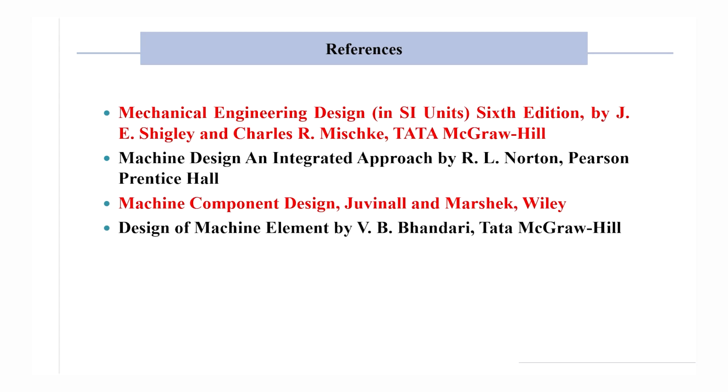We also studied, as per Buckingham, what will be the maximum allowable tangential load on the gear considering wear. And we found that the maximum allowable tangential load on the gear considering wear is more than the actual tangential load which was acting on the gear. And therefore, in the case of bending and in the case of wear, our worm and worm gear drive has satisfactory parameters which were determined during the design process. Thank you.